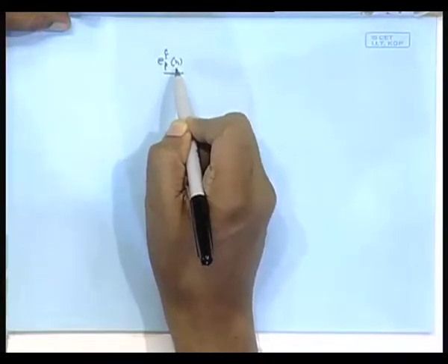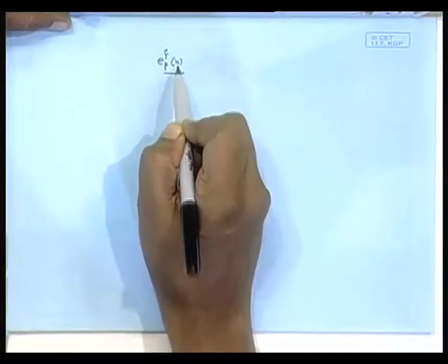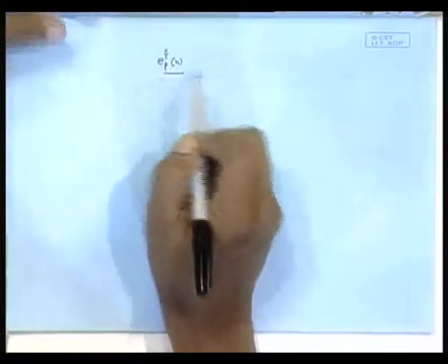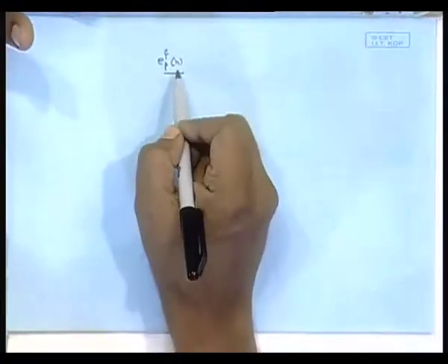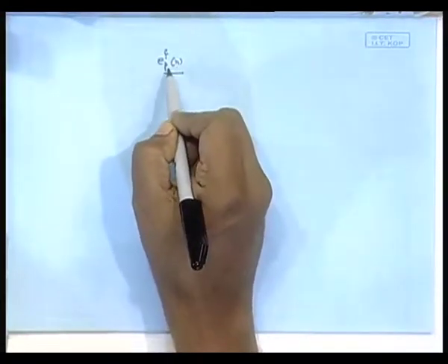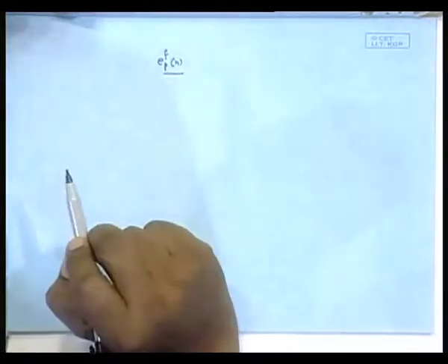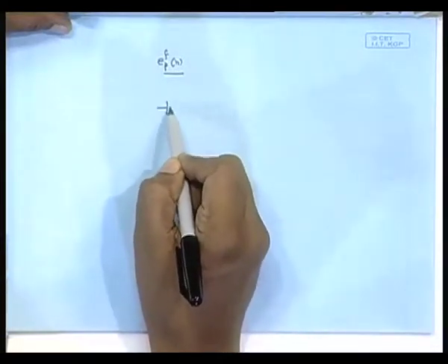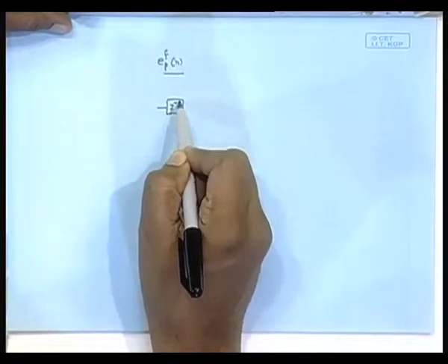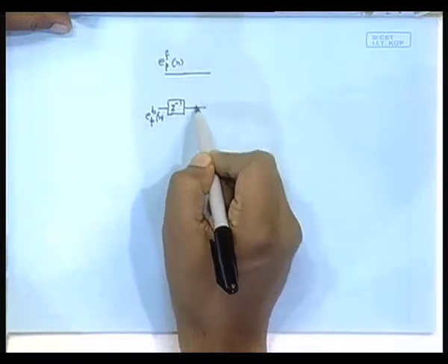If I write EPN, actually you remember there was a subscript P comma N, but then I dropped it. Ideally that subscript should be there. It means that you take data up to nth index, based on that do the least square minimization, that is orthogonal projection, find out the error, and take that error's last component. But since it is still n only here, I am dropping that n, assuming that we do understand the implication. These two signals, this one and this one, that is more important here.